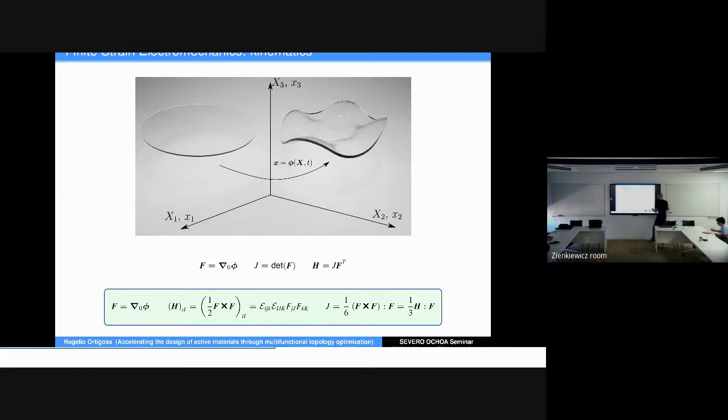And then the Jacobian can be expressed like this. Why do I prefer this? Because typically in nonlinear continuum mechanics, you are going to compute first and second directional derivatives of these kinematic entities, and this makes my life easier. What notation you prefer doesn't matter. In my case, I prefer this because it's going to make my life much easier.